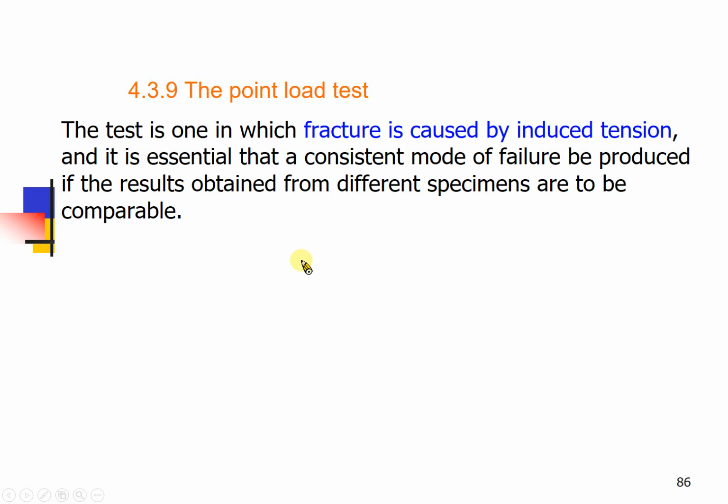The rock fails under tension stress, actually. Can you imagine? If you have a rock and you apply a point load on it, then it will be split into two pieces. Actually, it will fail by the tension stress. I will show you another typical testing method to measure the tensile strength of rock. We call it the Brazilian test.